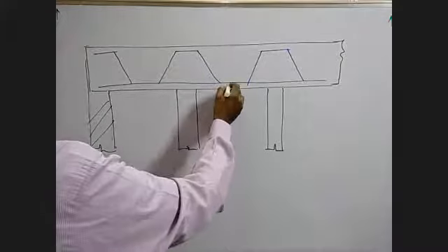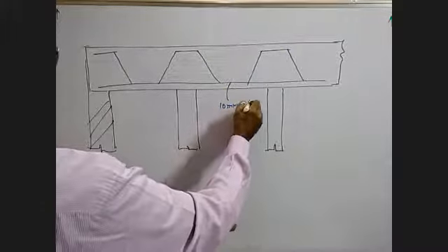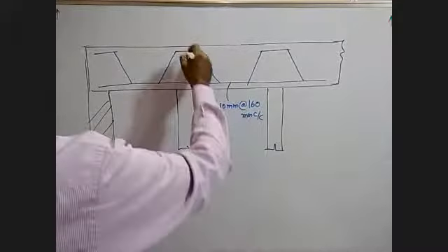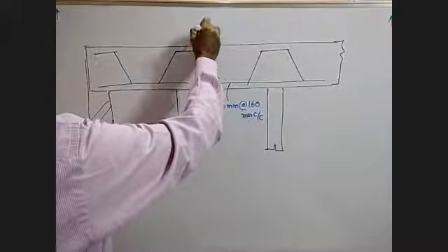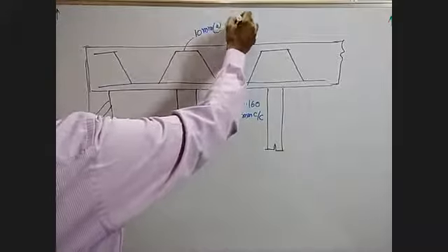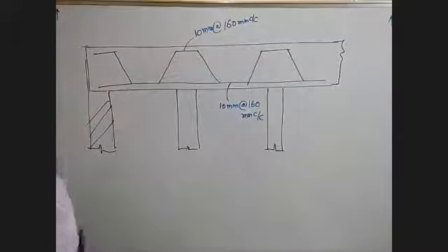This is the main reinforcement, 10 mm at 160 mm center to center. This is 10 mm at 160 mm center to center.